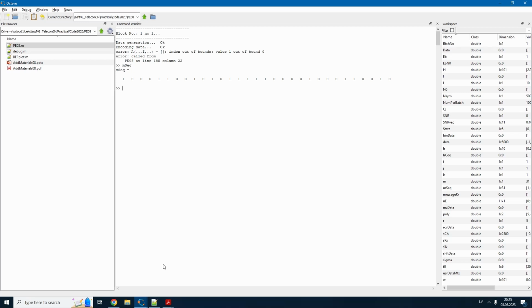Finally, the autocorrelation function for this M sequence can also be calculated by using the XOR function. So again, the value of the lag will be XOR of the M sequence. However, we need to convert it into a bipolar process, minus 2 multiplied by the M sequence plus 1. Also, we want unbiased. If you remember, today we specify 2 signals for which to calculate cross correlation. Now, if you specify only one, it will automatically use this signal as the second signal. That would be the concept of the autocorrelation function: correlation between a signal and its own copy. Now we can plot this, or maybe stem, with lag on the x-axis and values on the y-axis.